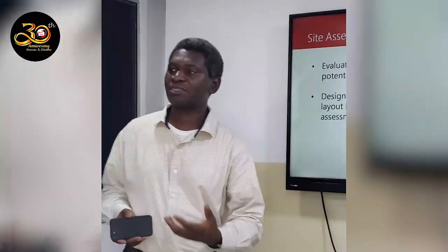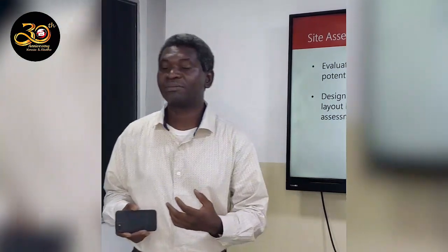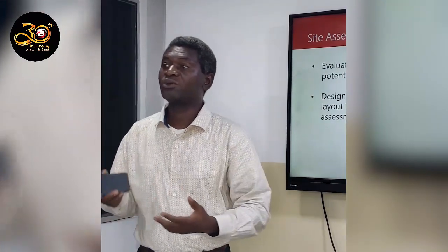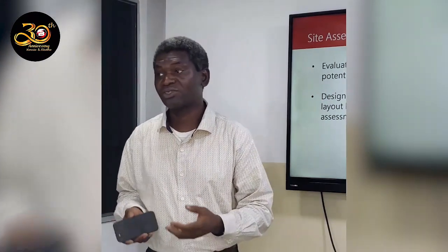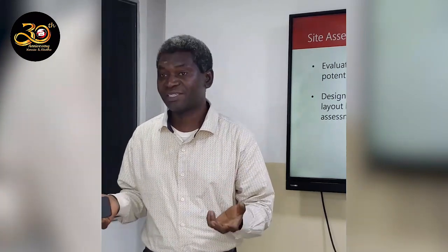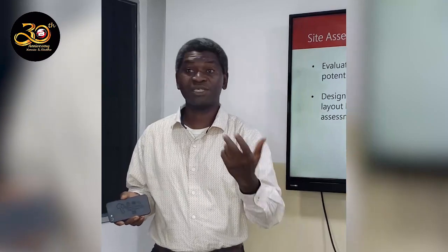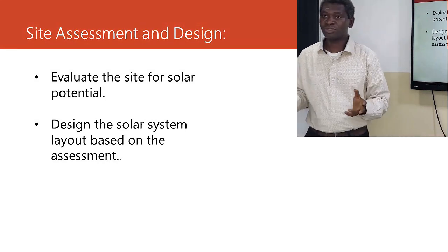Okay, hello sir, please, where do you want us to put the battery? Where do you want us to put the panel? Even though you are the one that will advise them on the panels, because with the panels you have to look at the orientation. There's what they call azimuth, there's what they call orientation, where the panel will face, where it can get more resources. Mostly, your panel should face the south. Your panel should always face the south, because in the early morning the sun comes from the east, but your panel should face the south. So you have that decision to make to tell them.